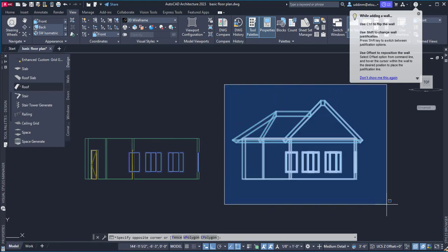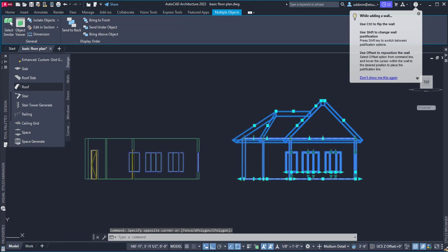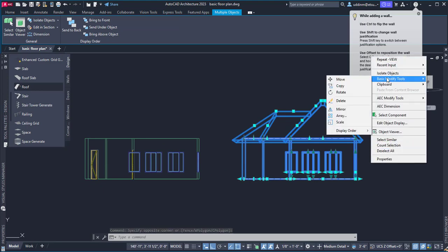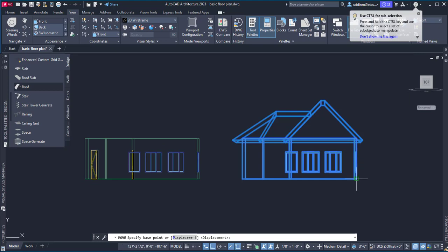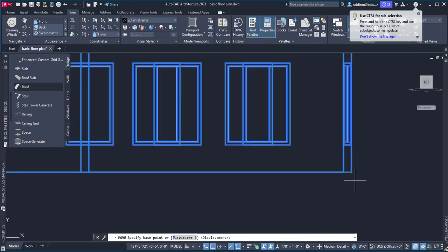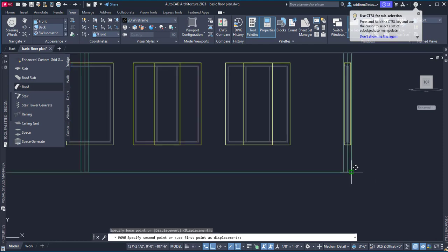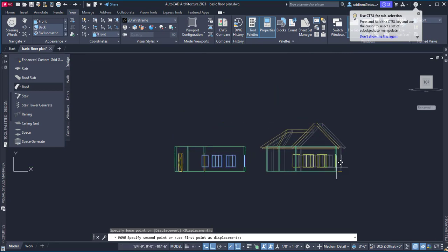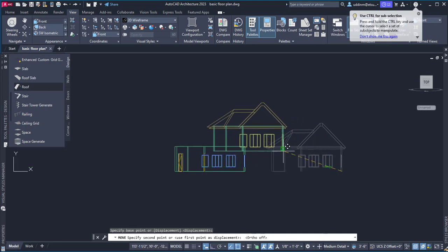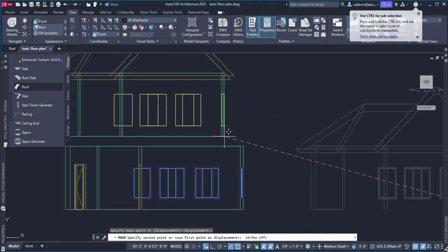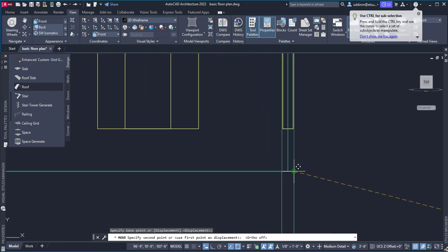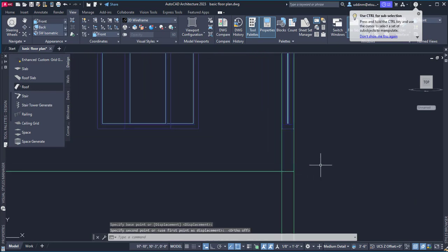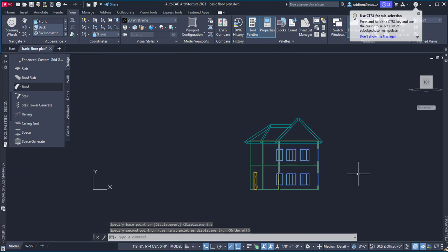So I'm going to put a box around here to select it, right click my mouse button, select Basic Modify Tools, and then Move. And now if I come to this little corner here where the box is, that little green box, I want to use this as my reference point to move. Click there, and then I want to stack it over here on top. With the orthogonal, now I can toggle orthogonal off, which is in this case F8, and now I can move it up until I make sure these green boxes right here connect, and the plan has now stacked.